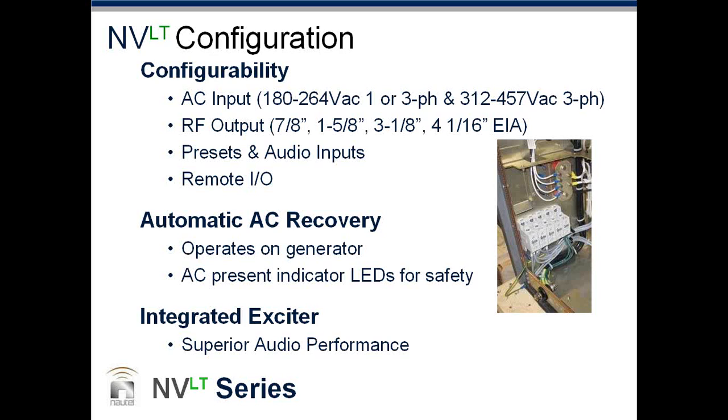Then we can orient them in three-phase fashion by putting an equal amount on each phase to get a three-phase version of the transmitter, which operates on the same range of voltage, or we can operate them as a 280 volt. In other words, we can do them as delta or Y when we're in three-phase mode. That's correct. So you can change that at a moment's notice.